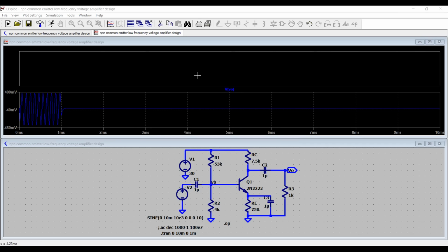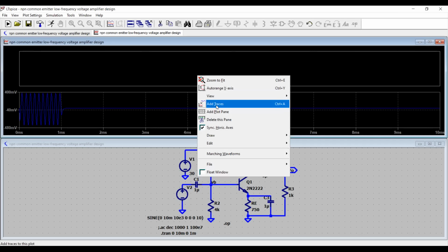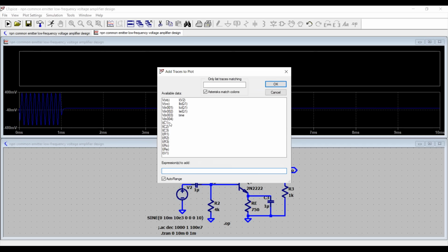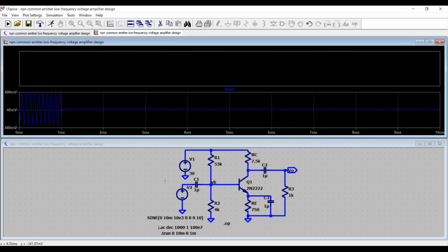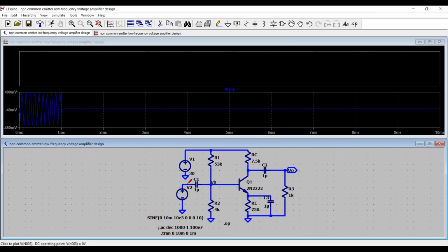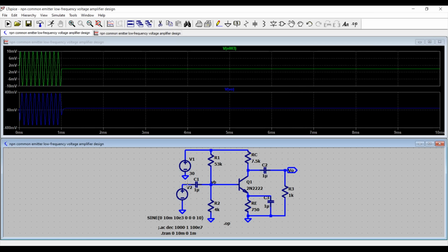And on the upper part of the graph, I want to add the trace. Will plot the input signal. So voltage at the node. So I can't see the nets here because I haven't labeled them. So why not just click on the schematic and have the probe help me do that. So now you got to see that I have these beautiful waveforms. I'm going to zoom on the portions.